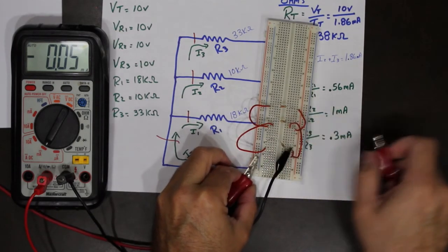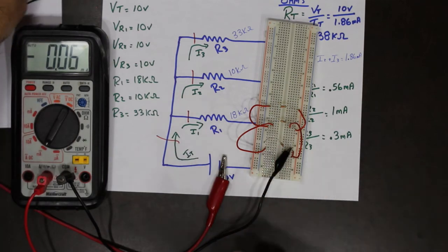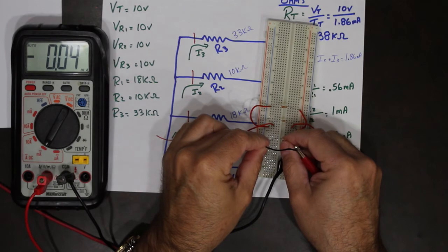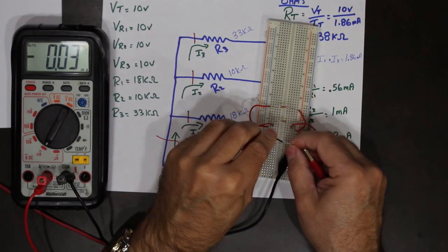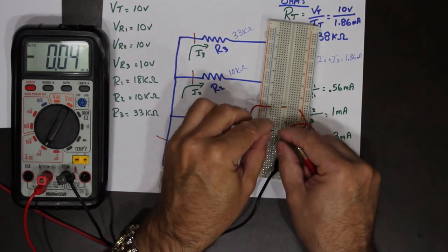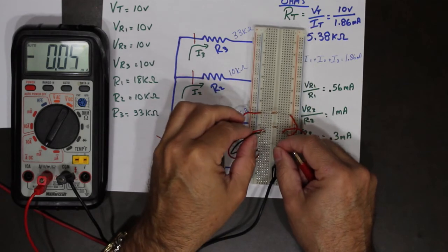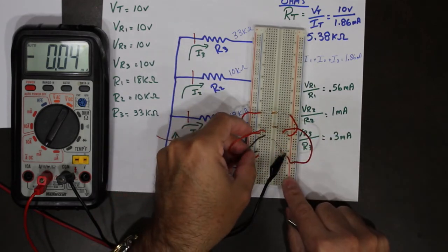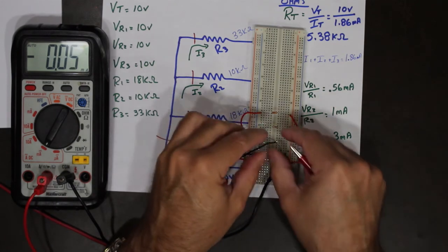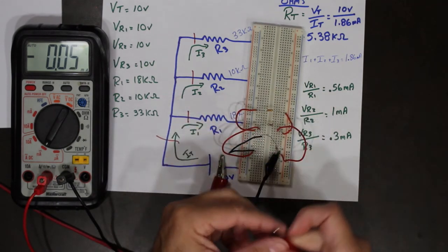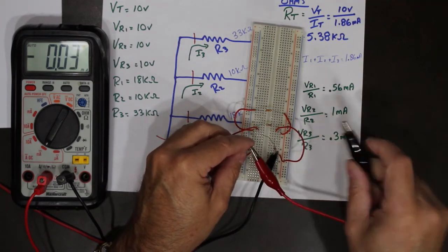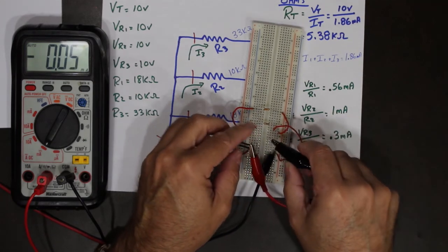So let's pretend I was going to cut that wire. So let's pretend, snap, I just broke that wire right there like that. Okay, so now what I want to do, oops, sorry, this got to go here. I just snap that wire. So now what I'm going to do is I need to close up that gap with the ammeter.